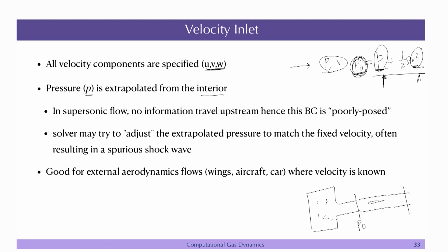So, what we do is that we fix the P naught, okay, and then fix either P or V, okay. So, that basically your P is fixed and the V will be adjusted such that it goes to the P naught value you desire, okay. Or if you fix V, then P will be adjusted by the code in such a way that P naught is fixed, okay.